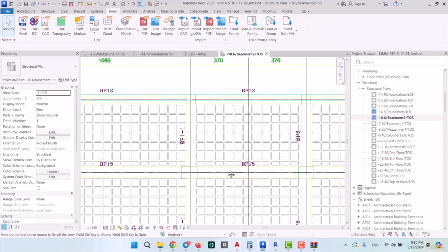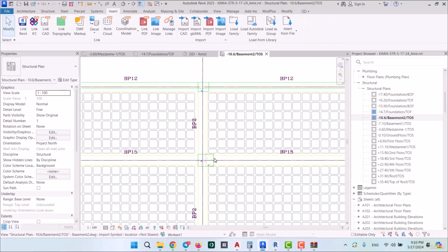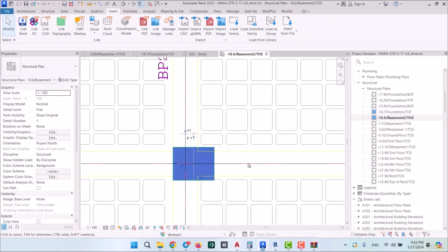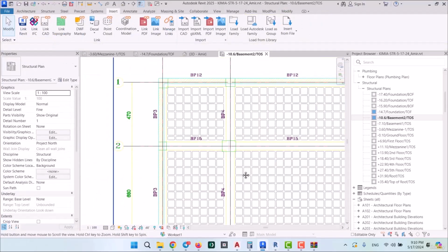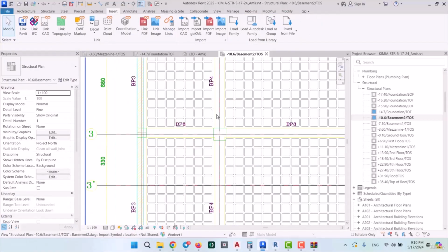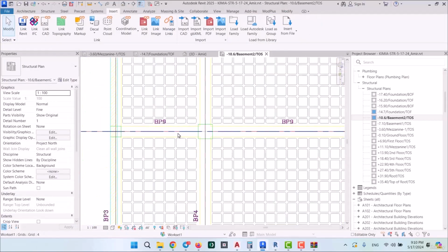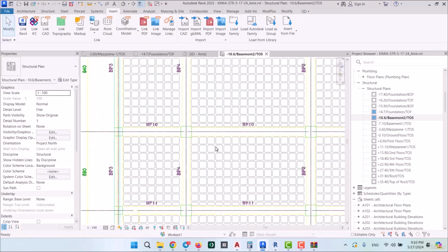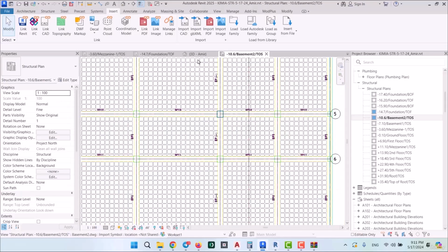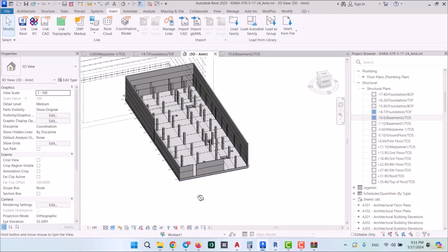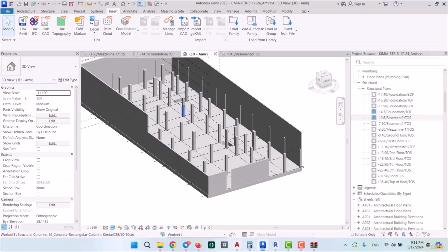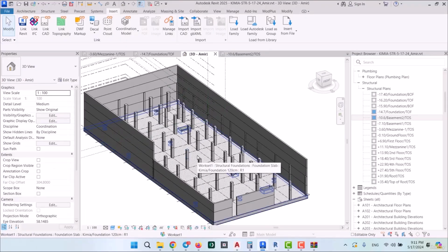Now once again, I'm going to skim them real quick to make sure the column sizes are all correct. I'll set the draw layer to foreground and then take a look at all of the columns to make sure that their sizes are relevant. Also, based on what we've observed in the sections, there aren't supposed to be any changes of size for these columns in this level, and they also seem fine to me.